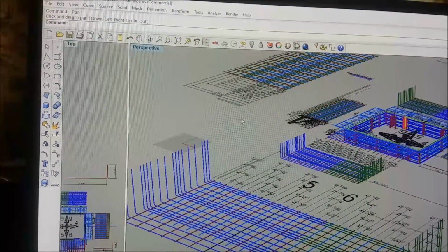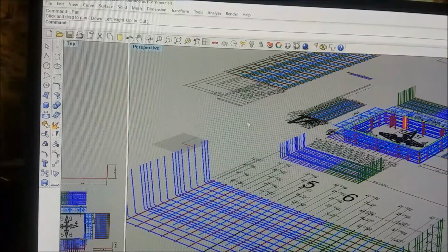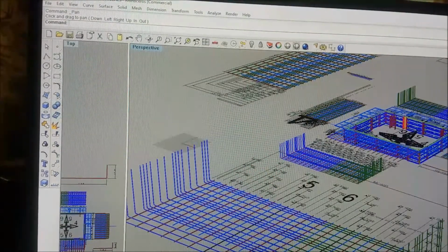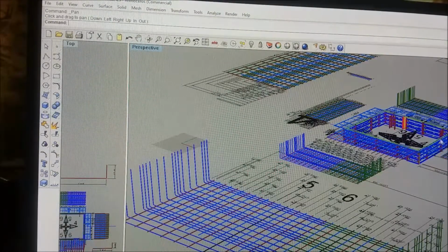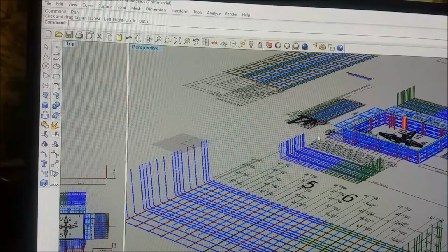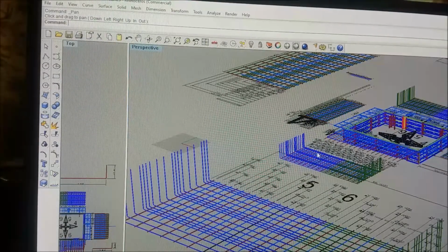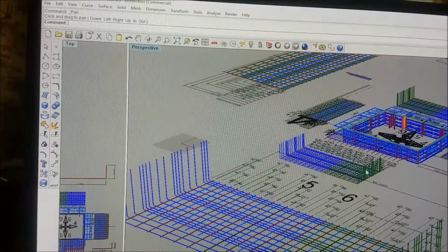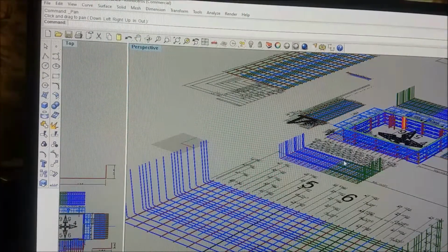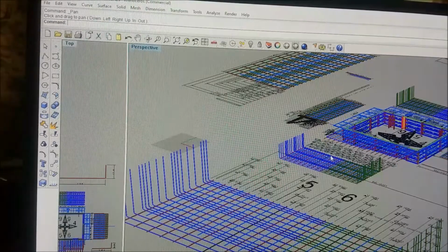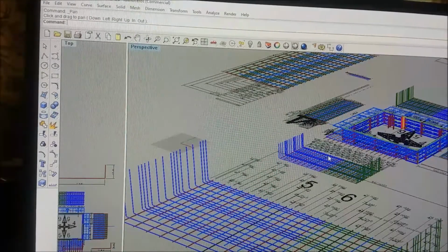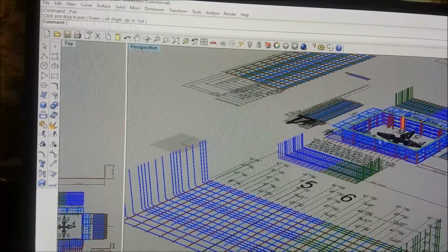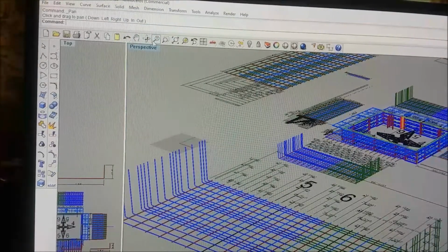Okay, what we're looking at here is how you use rebars. What we're looking at here is a slip form poured water cistern, 37,840 gallon. You'll notice that there's a bent rebar here, and one comes from the other side. They overlap about 3 feet in the middle. No use cutting a piece of rebar off 15, 16 inches long and throwing it on the ground. Just put it in the wall. Anyway, this is the slip form with the rebars.